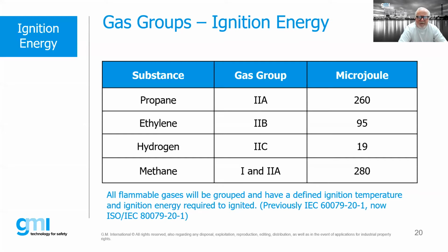So this is a very significant factor that we have to also take into account when we're selecting equipment for use in hazardous areas, is how much energy does it actually take to ignite these gases? And not all gases have the same amount of energy. And in this case, hydrogen is very, very easily ignited. If we have a proper mixture of hydrogen in combination with air in what is called that flammable limit, it doesn't take a whole heck of a lot of energy to ignite it.